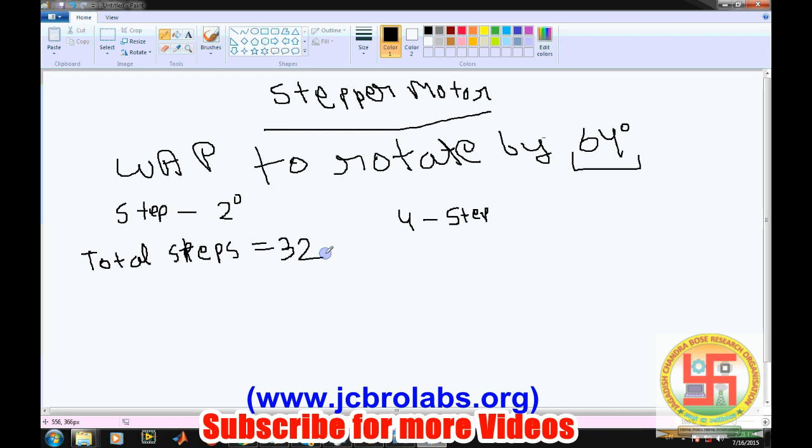Total 32 steps will be required, and further, because we have a 4-step sequence, we need a total of 8 repetitions of these 4 steps. Now let's go over it once again. We need to rotate by 64 degree. One step angle is 2 degree, which is the motor specification. So we need a total of 32 steps to rotate by 64 degree.